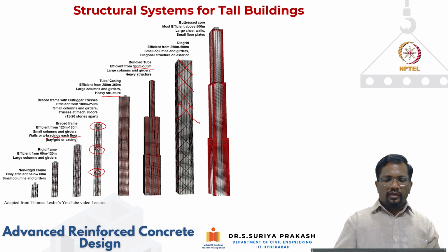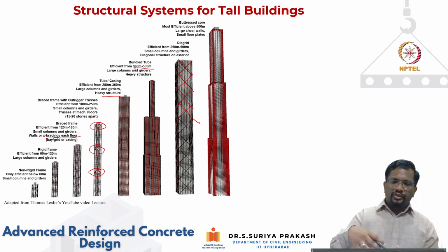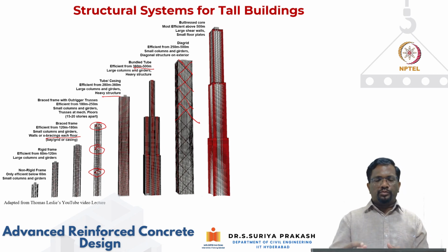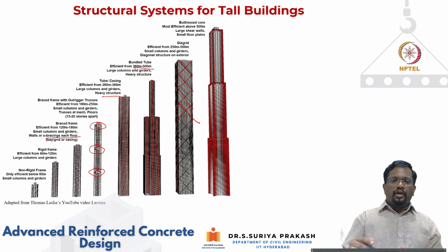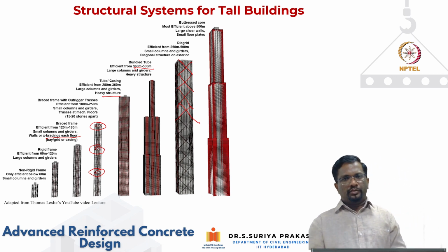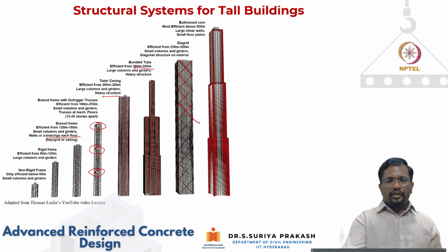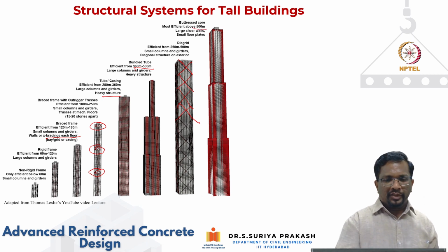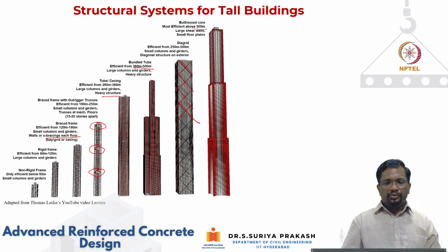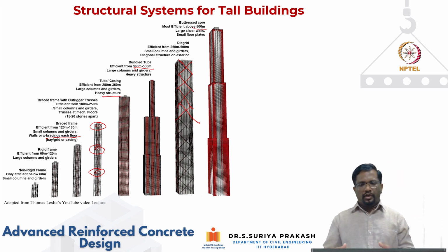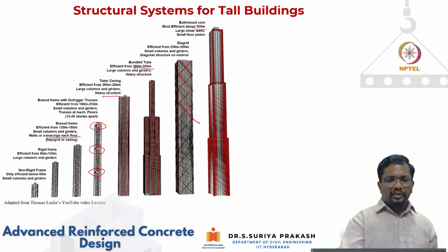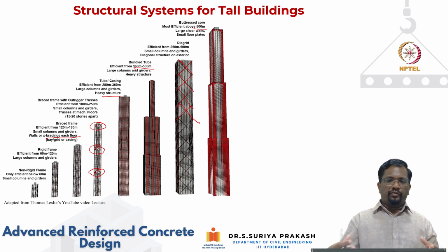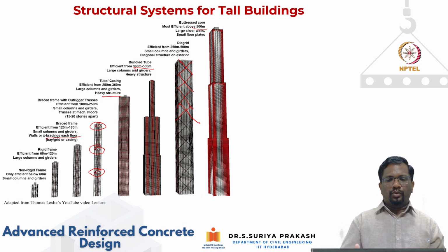And there, in fact, the core system will be kept inside, and the core design would be much heavier, and it will be very involved. In fact, this is the same buttress core system that was used in Burj Khalifa as well, and usually they are very efficient at more than 500 meters. You're going to use large shear walls at multiple locations. In addition to that, you're also going to have this kind of a tube system along with the heavy cores that you're going to have.